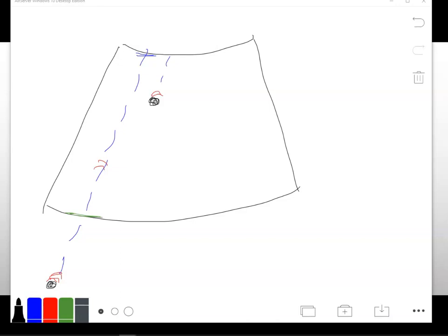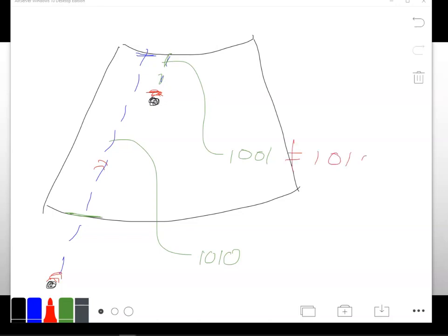Now, this is the beauty of binary encoded excitation, is that on this line, the first line that we send out, okay, if we encode that with the code 1010, and then we encode this second line here with binary encoded 1001, when this echo here comes back to us, remember it came from the first pulse, the 1010 pulse, and so the binary information in it is going to be not equal to 1001, but it's going to be 1010, and the machine will see that difference and throw out this echo and not even display it for us. Okay, so that's how binary encoded